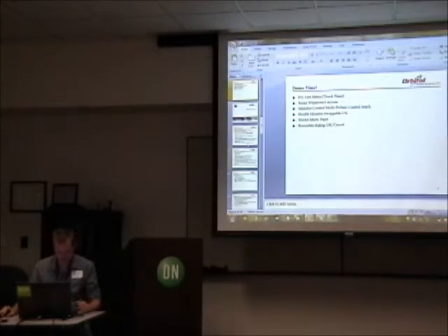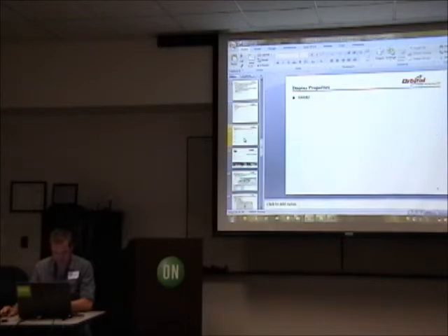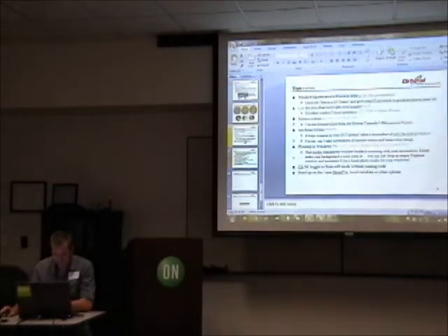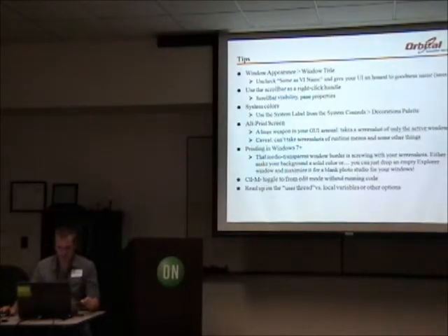Tips and tricks, and let's just screen through them all in here. Did you know? Oh, here's my colorblind test. Do you all change your default window title to get rid of the .vi? Yeah, sometimes. Good, it's better that you do. Users don't care you're developing in LabVIEW, or they shouldn't even know. In professional software, I don't know whether something's written in C or Java, and probably better that way, right? It sticks out like a sore thumb. Everybody's like, what does VI mean? Is that important to me? No, just uncheck it and give it a good name.